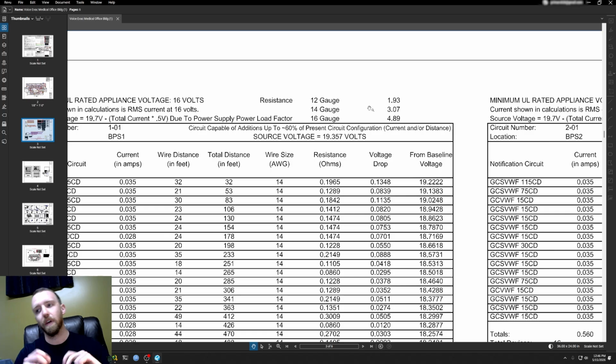If you have a bigger wire gauge number, you have a smaller, more constricted wire, which means it's going to take a lot more force to get the electricity to move through that wire, and you're going to have higher losses. So the impedance is going to be greater for a greater gauge number of wire. But if you decrease the gauge number, you increase the diameter of the wire, which means you're going to have less losses. It's going to be easier to flow through that. So that's what was indicated here.